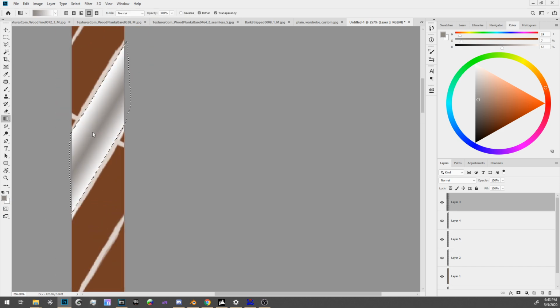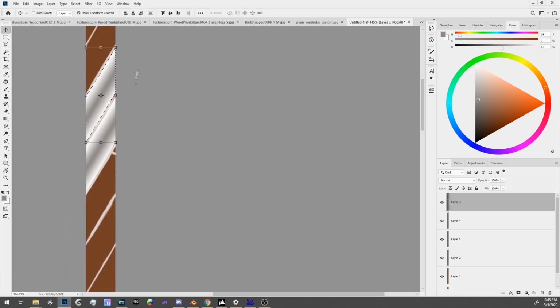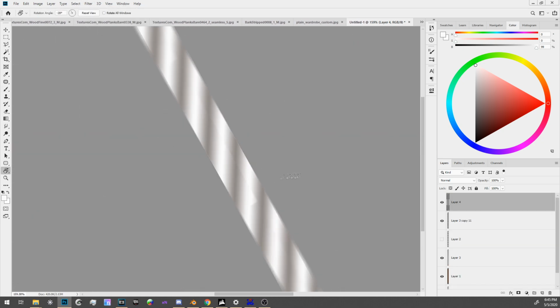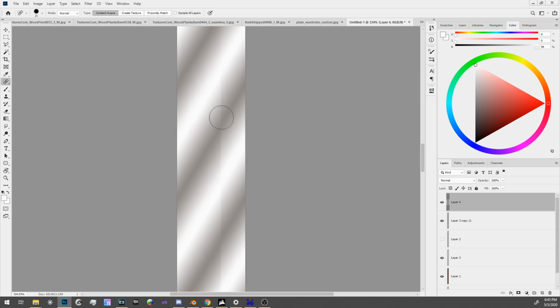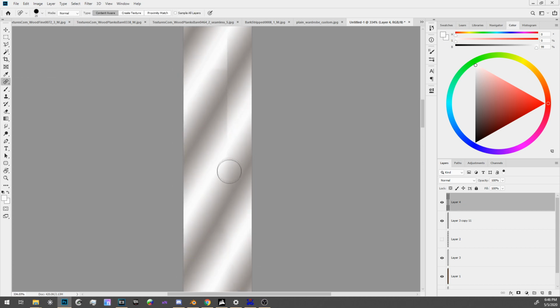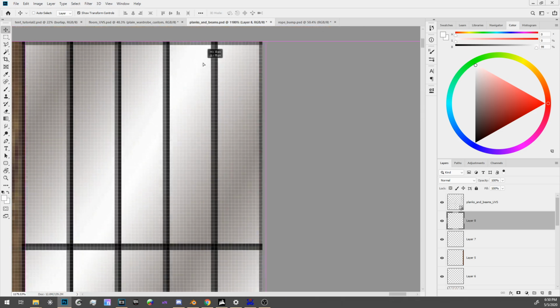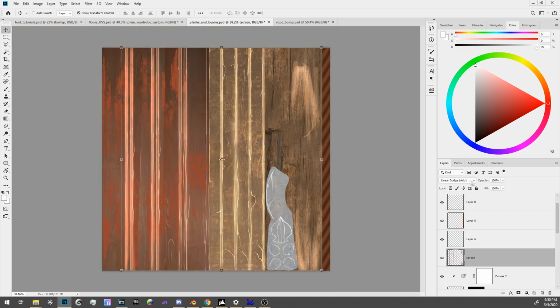The trick here is to create a pattern that will be seamlessly tileable. For that, I draw diagonal lines and then make a small gradient in between them. I duplicate this gradient along the length of the rope with equal spacing. Then I use offset and patch tools to smooth it out and finally copy it into a previous file where I position it very carefully. It has to match the UVs of a rope perfectly. I turn its blending mode to multiply and then it's ready.